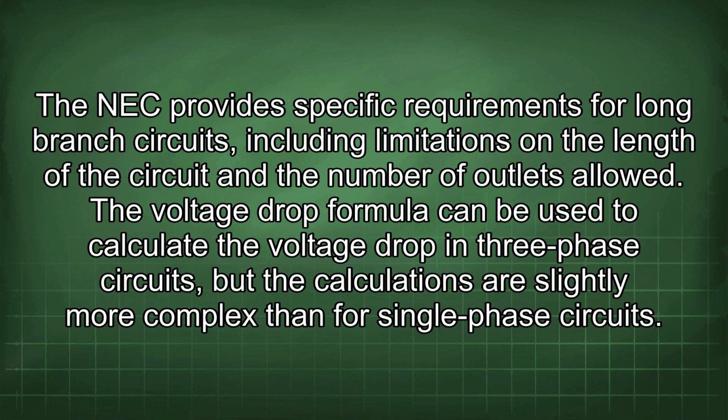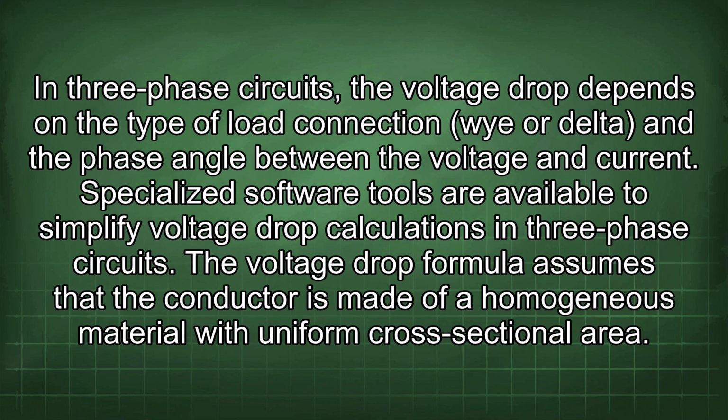The voltage drop formula can be used to calculate the voltage drop in three-phase circuits, but the calculations are slightly more complex than for single-phase circuits. In three-phase circuits, the voltage drop depends on the type of load connection, Y or delta, and the phase angle between the voltage and current. Specialized software tools are available to simplify voltage drop calculations in three-phase circuits.